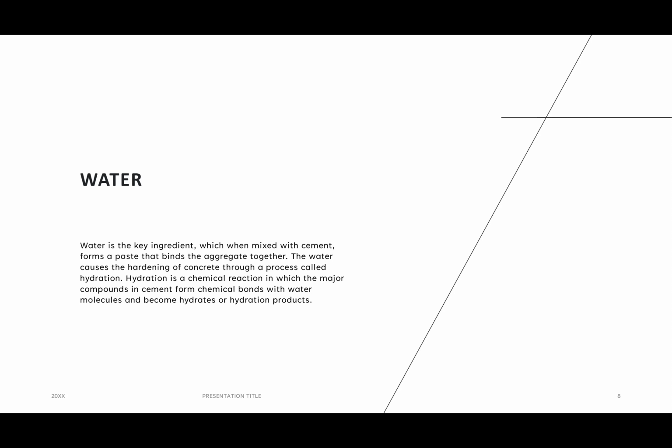The ratio of the amount of water, minus the amount of water absorbed by the aggregates, to the amount of cementitious materials by weight in concrete is called the water cementitious ratio and is referred to as the w/cm ratio. This is used to determine the amount of water that is needed. In general, less water produces better concrete. However, concrete needs enough water to lubricate and provide a workable mixture that can be mixed, placed, consolidated, and finished without problems.